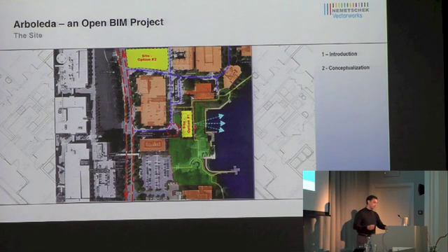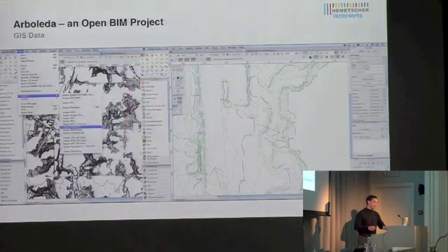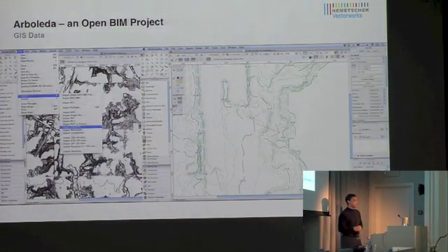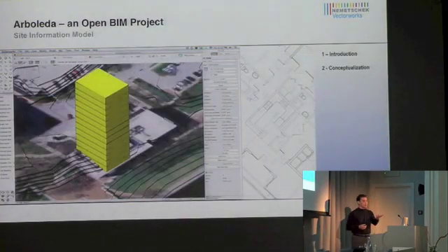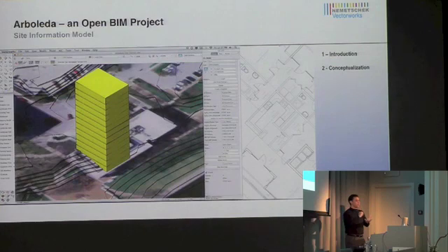I decided that I had a site, I had a place, waterfront, and also I had access to geo-reference information. I have access to the county information, get that geo-reference information, put it back into Vectorworks, and from there created the first model, the site model. Once we have the site model, we created a quick mass model just to put it on top of the building.